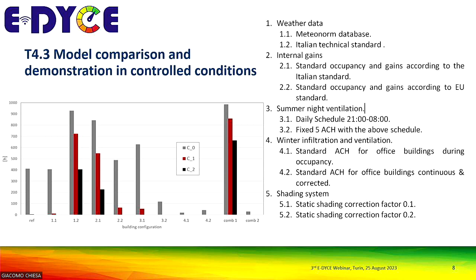According to the relevant standard, this building should be in class C2. That means 2 degrees of difference from thermal neutrality for the measured operative temperature. The red would be class 1, which is for a weaker class of people, like elderly or sick people, which is 2 degrees. The one before was 3 degrees.